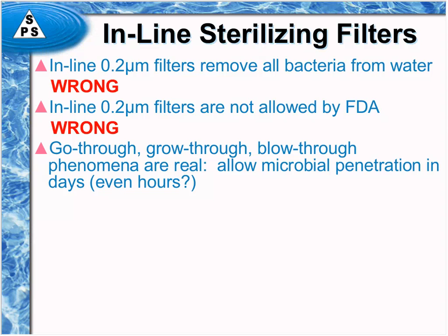There's the phenomenon here of microbial penetration called go-through, grow-through, and blow-through. Go-through is where the organism actually winds up finding a larger pore and gets through the pore without impinging on the media or permanently sticking to the side of the media as it goes through the tortuous path and gets through to the other side.